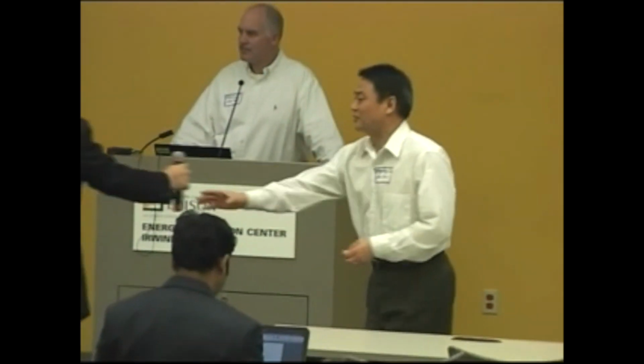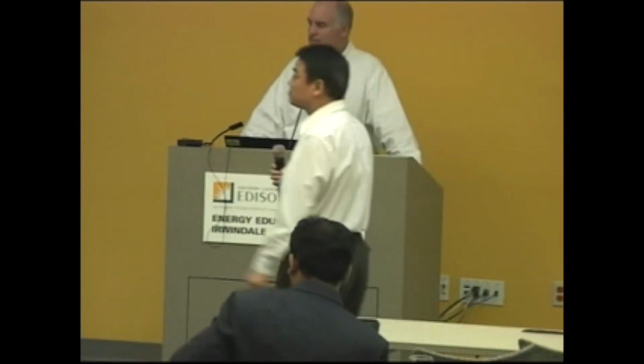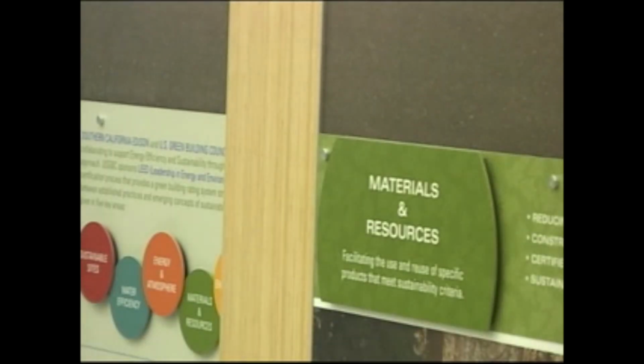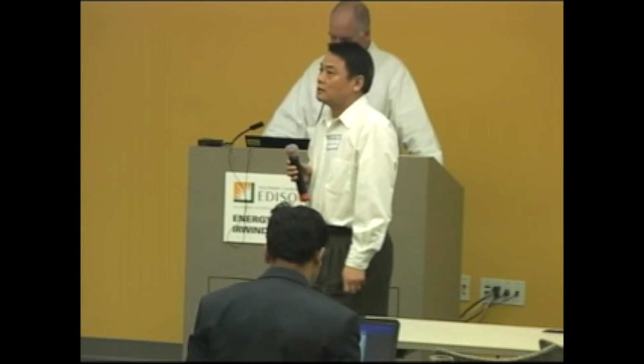As one last comment on this issue, for that slide where he showed the temperature fluctuating, I think it's important to put it in context with a set point inside the building, because if you're holding the set point more accurately, that savings can be considered actual savings. Without that context, it does show you're providing less cooling.